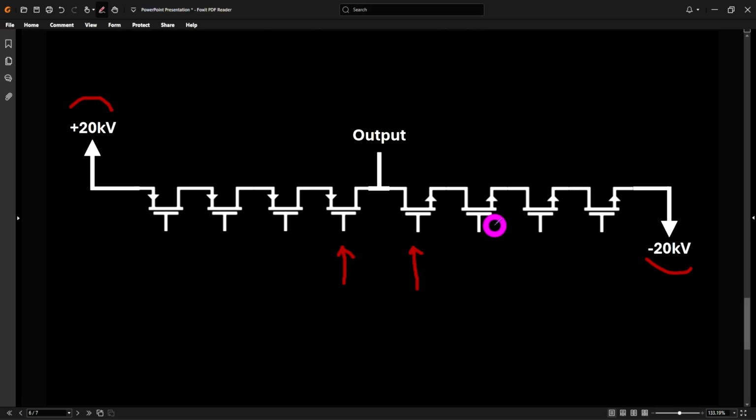A cascode architecture is a very specific combination of a common source and a common gate amplifier, where you basically bias the gate of your common gate amplifier as an AC ground. In this case, that's not what you're doing. All of these gate voltages have to be driven with some signal from the outside. And if you think about that, that's because if I fix any of these gate voltages, let's say I fix this voltage to some fixed bias in DC, and I apply no AC signal to it.